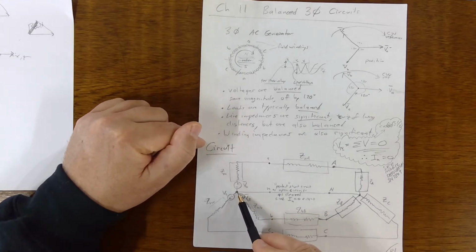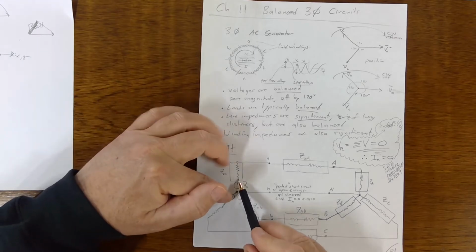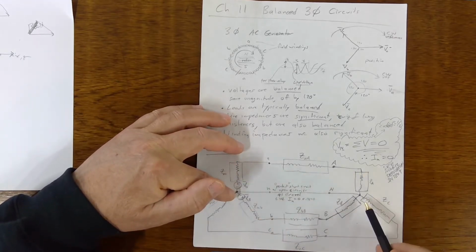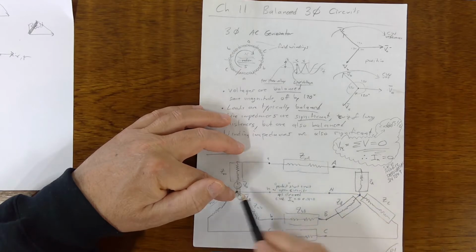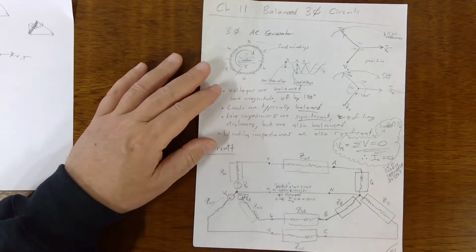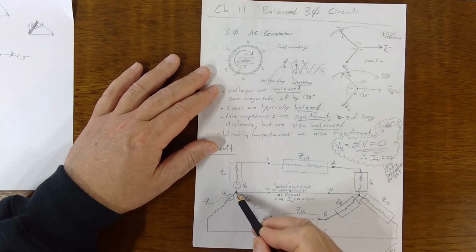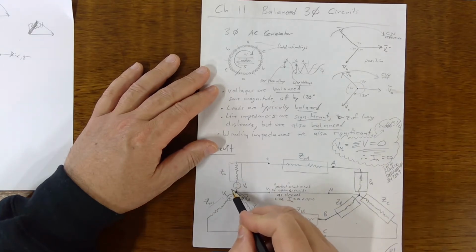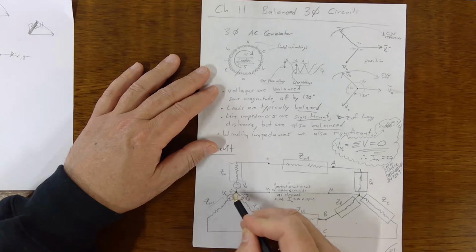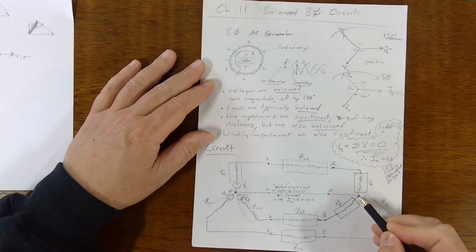This is the source node where we're starting, and then we're adding a voltage up to that, and we're dropping the voltage across all of these things. The voltage at this point is 0. So it's 0 here and it's 0 here. It's basically 0 across this neutral line, all right? Because of this sum of the 3 voltages, 0, magic. And I could even throw a ground on here. You've got to ground something, right? And that's what you ground. So you could ground this too.